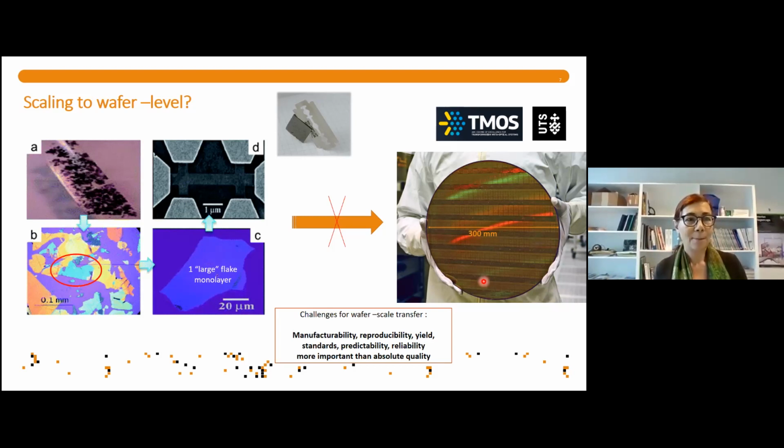I also want to remind you that the CTE of graphene is negative. So unlike most of the conventional thin films, this means that any thermal loads or mechanical loads which happen at the wafer level, CMPs and such, will probably lead to some type of failure.